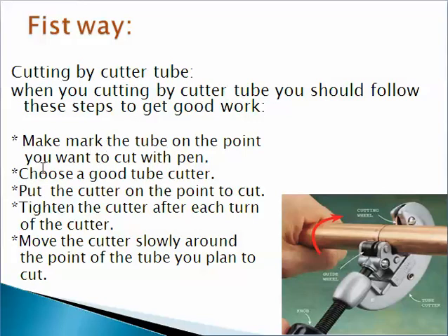First, choose a good tube cutter. Then, mark the tube with a pen at the point you want to cut. Then, put the cutter on the point to cut. After that, tighten the cutter after each turn of the cutter. Finally, move the cutter slowly around the point of the tube you plan to cut.